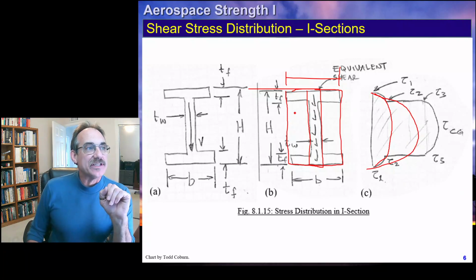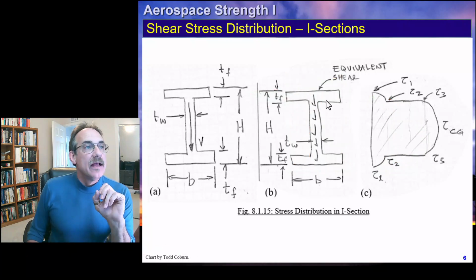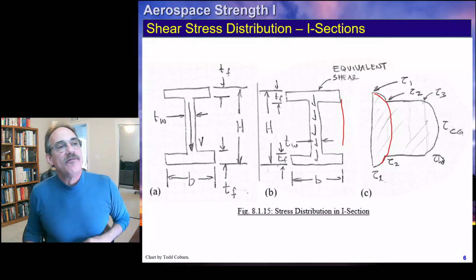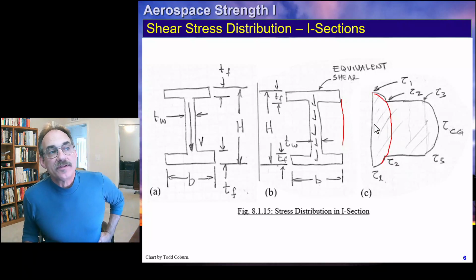In fact, what we have is a combination, because we have the I. The first little piece is pretty wide. So the shear stress buildup, let me clear this slide here. On the real section, if the beam were this wide, it's trying to do that. It's trying to go like this. But what we find is that VQ over I times the width dimension, at this point, barely above this, our width is this much. So we have a really low stress.